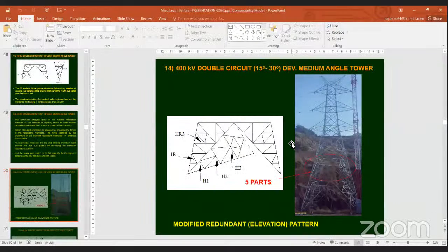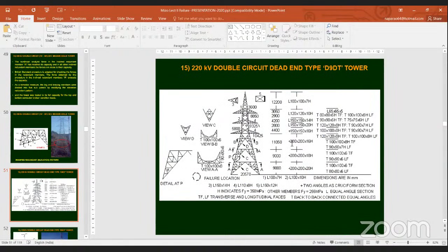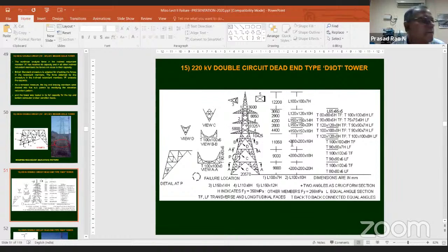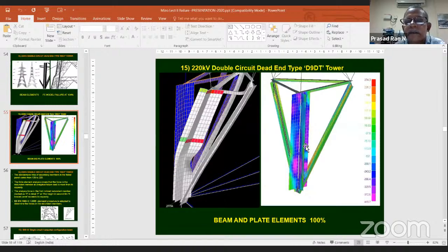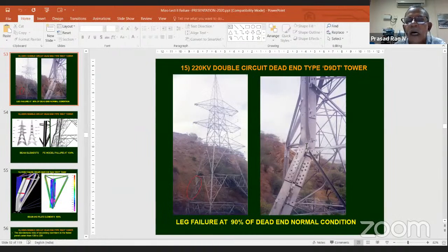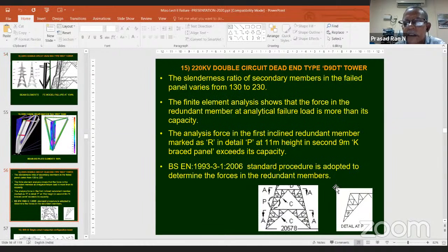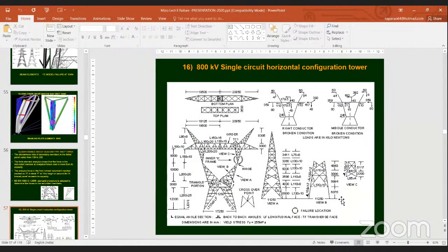Yes. Just one slide. I think I will show a comparison. This is another leg member cross section. How it is failing: you can see a local plate buckling type of failure, because the stresses in that flange have exceeded. That's why that portion has failed like a plate buckling. The test also failed like that. You can see here. See how, if two members are subject to compression, how it will fail. It is the example.